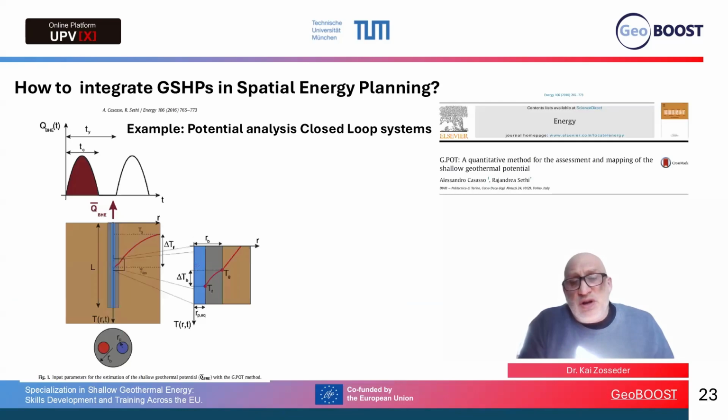Of course, you can assess also the potential of borehole heat exchangers. Here's one method. It's the G.POT method from Casasso and Sethi. So here you see all parameters on the left side, what you have to use here. So temperature, the length of the boreholes, thermal conductivities, and so on to assess this potential.